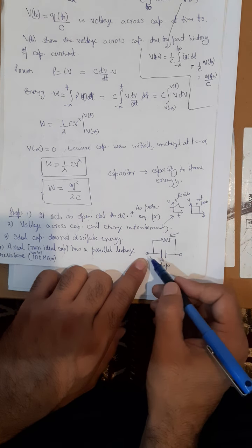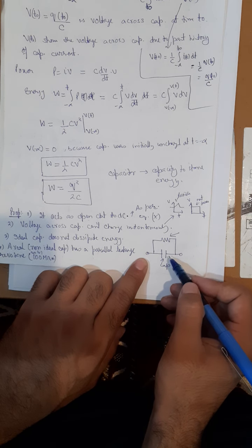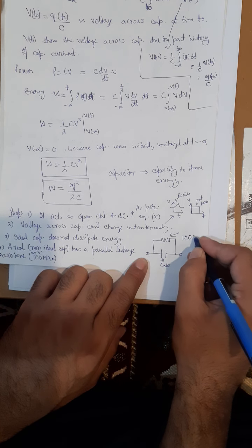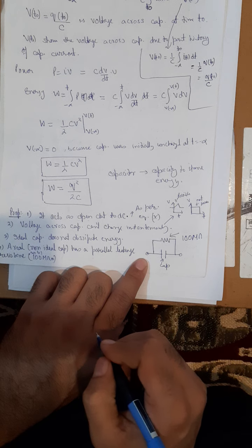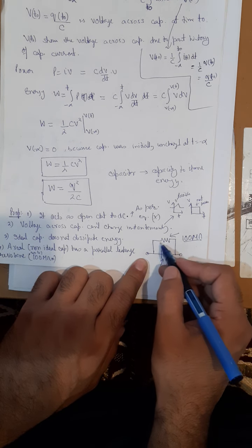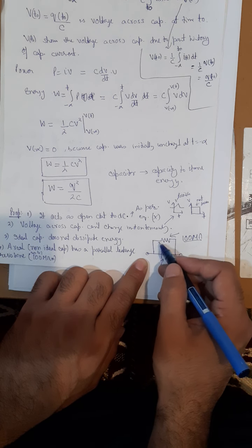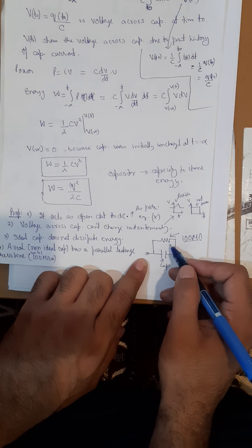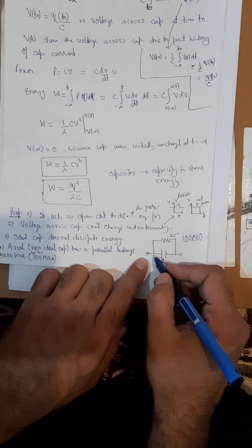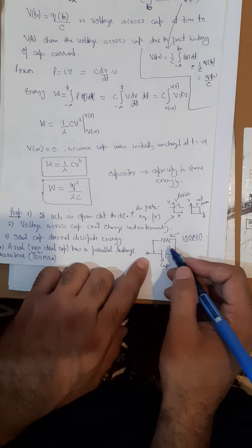Okay, so I am saying a real or non-ideal capacitor has a parallel leakage resistance. This leakage resistance can be of the order of hundreds of mega ohms. If there is some resistive component in the circuit, it will definitely dissipate some energy. Since this resistance is very high and it is connected in parallel, the current flowing in this resistor will be very small. Are you getting it?